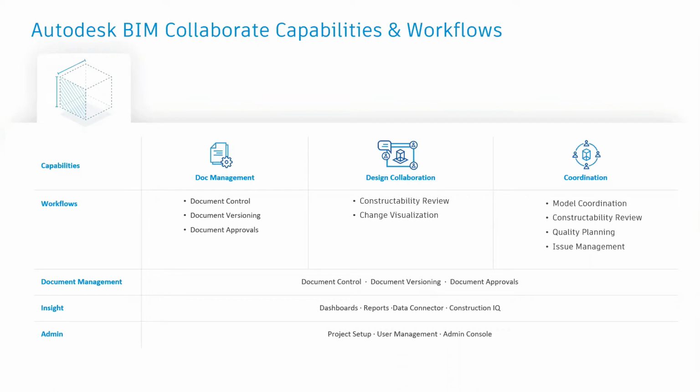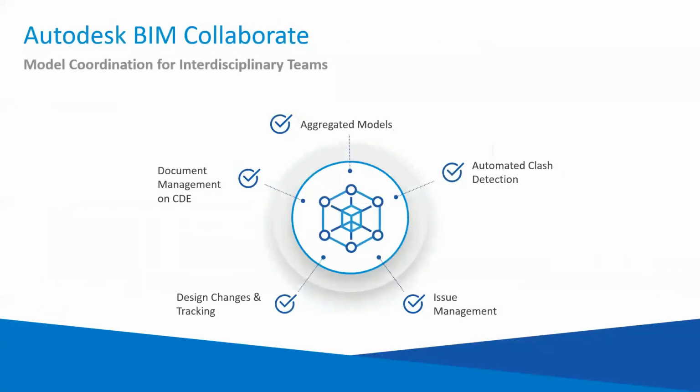So, moving on to the next slide. The next couple I'll just quickly go through. I just included these because they're a good indication of some of those workflows. Like I mentioned, you can create a shared folder, and that's typically the best way to do it, to have a common shared folder within the cloud, within the project, that the design authors and parties are uploading their models to, and that is the key to this automatic clash detection.